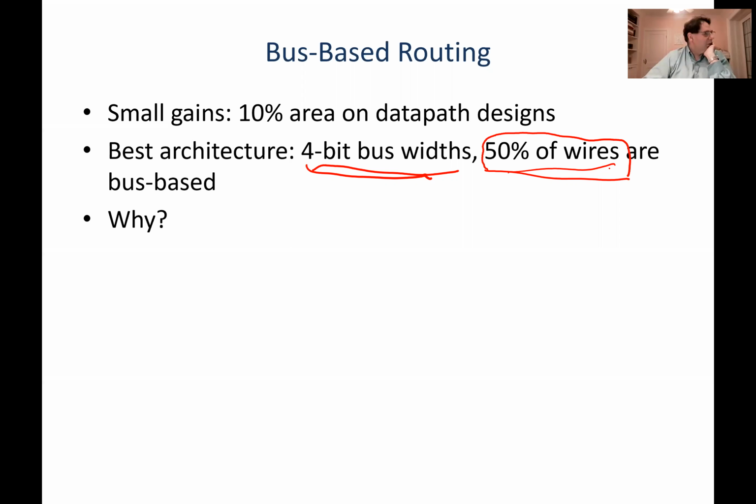Yeah, so Evan's got a good point. How significant is the CRAM area compared to the MUX area? So they fundamentally can only, they can't save the MUX area with the approach they're taking. So what they're doing is they're taking a bunch of wires, okay, so a regular routing channel, and let's say I did a bus width of 2.